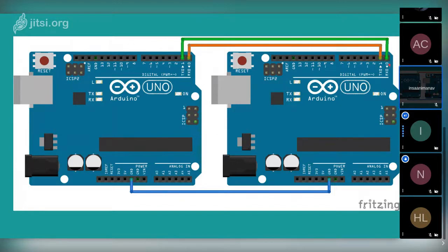So if we are uploading a program to the Arduino, we should never have anything hooked up here, because it can and it will cause difficulty in program uploading. We'll see errors from the IDE saying maybe programmer not found or something. So this is how it works in case of an Arduino.